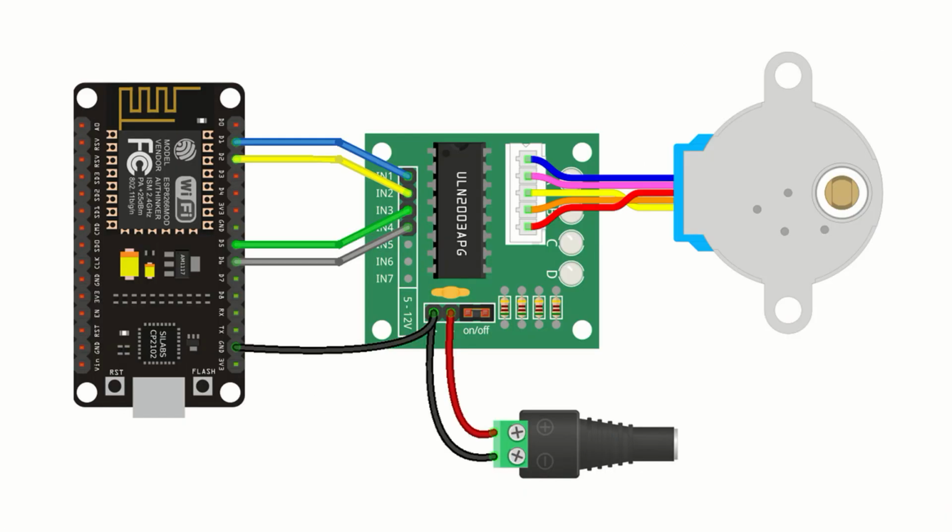If you want to interface it to your board, you should remember you require a driver IC, because again the motor draws a huge amount of current. So you require at least an IC like we have discussed, L293D or ULN2003 IC, with 4 inputs and 4 outputs. The fifth one is common, red is common. You can see the color code also: first is orange, then yellow, then pink, then blue.